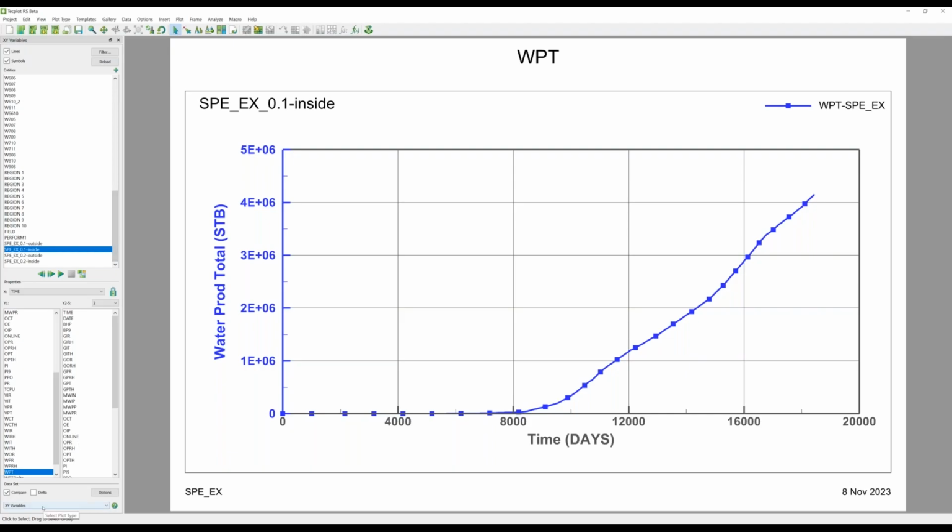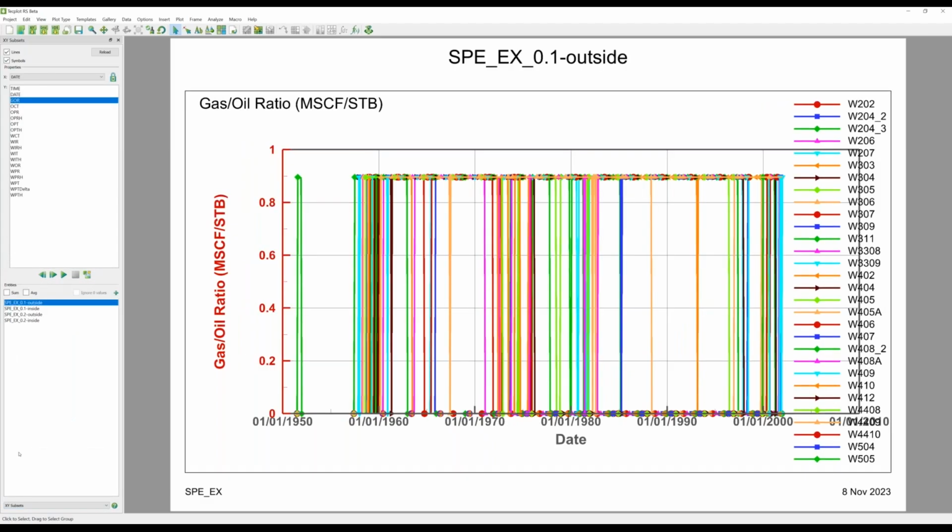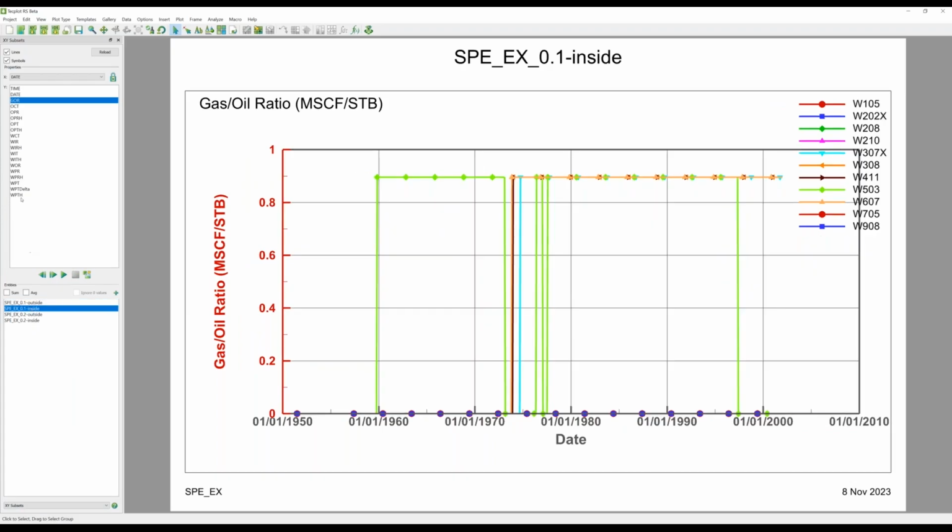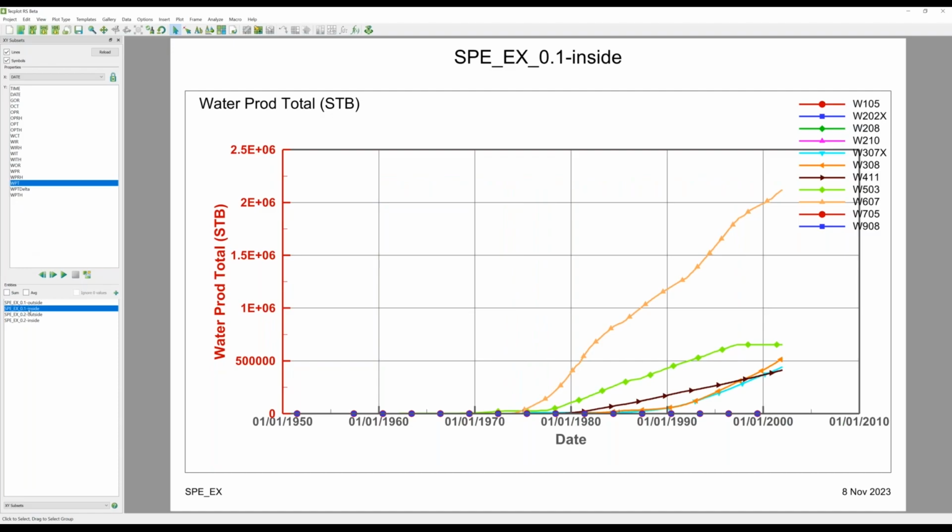And if you're a seasoned user, you might have always passed by this XY subsets plot type, and you're wondering what is that, and that's exactly what it is. If you have groups created, you could take advantage of the XY subsets. So I could jump into my XY subsets and do a full analysis on just that selection set of what wells fall inside of that 10% tolerance band. And now I'm just looking at the specific entities that fall within that range.